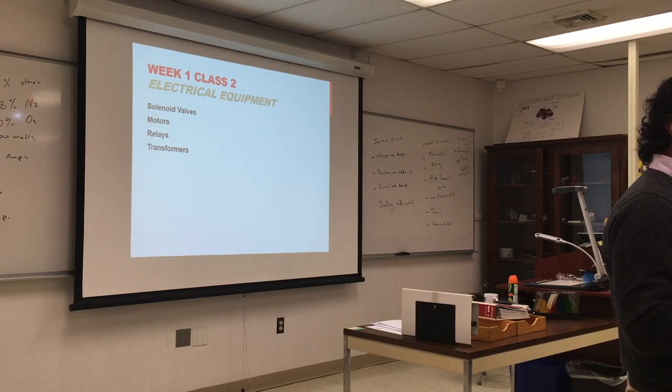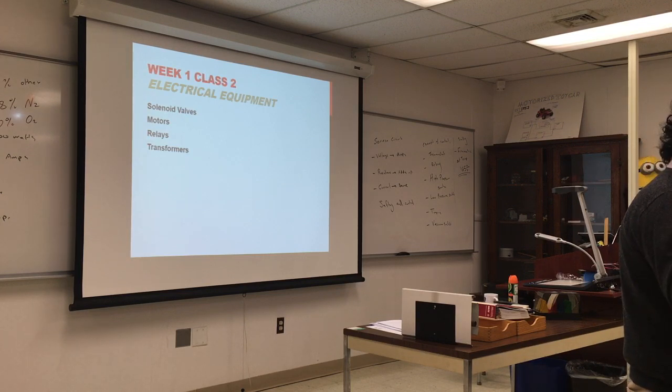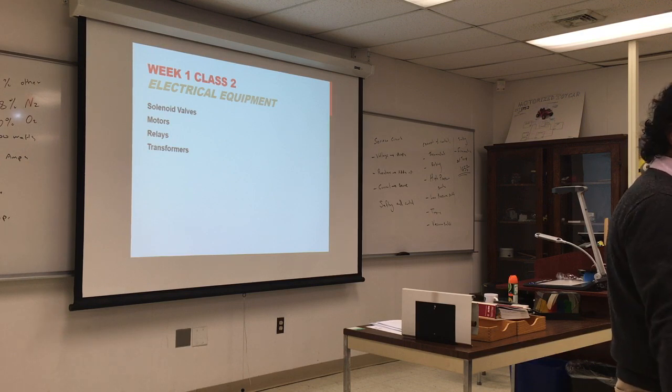Yes, if you have an indirect water heater that is heated by your boiler, you probably have one of those as well. This will have a thermostat that will turn it on, and it also has an aquastat. This aquastat will maintain the water inside the tank within those two limits, which are 140 and 180. So you're going to take water from that into your shower. Once it drops below 140, it will turn on the boiler.